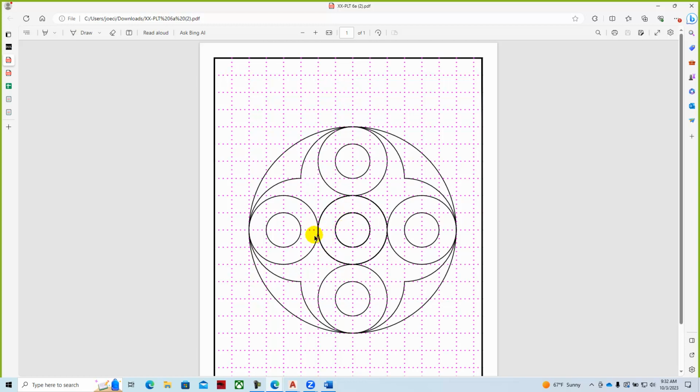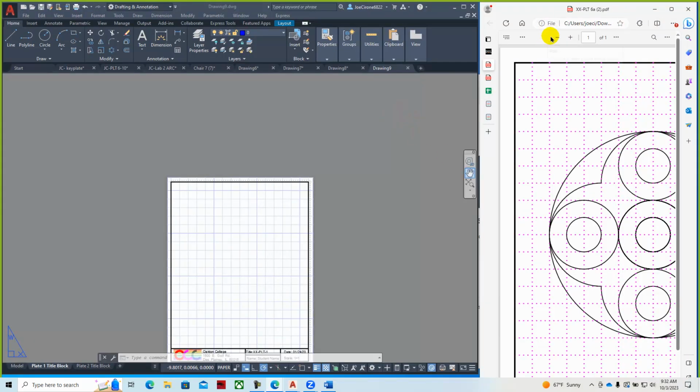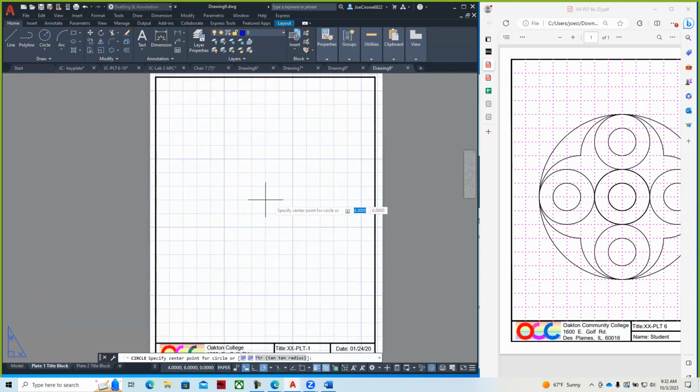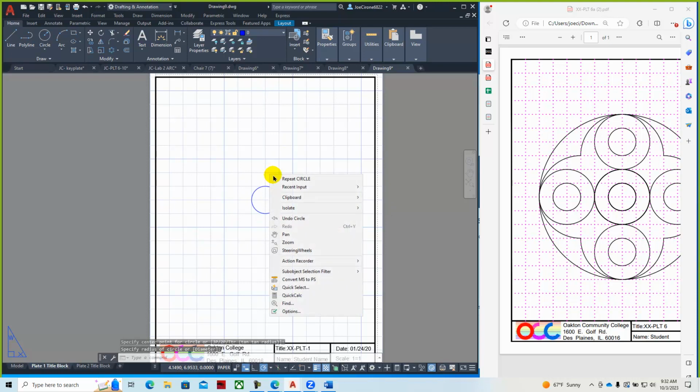The templates are designed to show you how to use these different geometries like center, radius. You can also use other circle creation techniques, but it's just a general design project. So we start off, I'm on layer 0 and it's blue, and I draw a circle. Notice that my cursor is only moving within the grid and the snap because they're both enabled. And then you just go ahead and draw a circle and repeat.